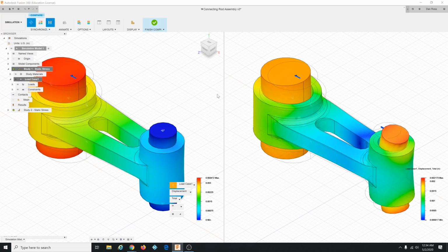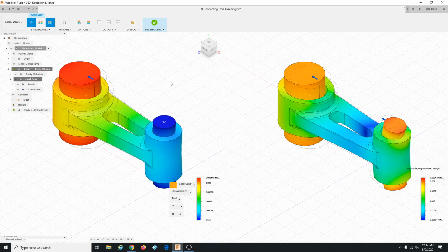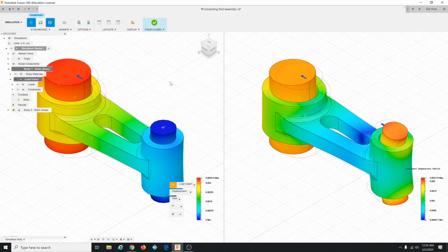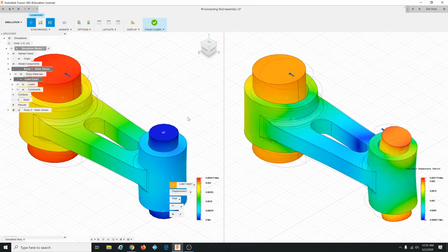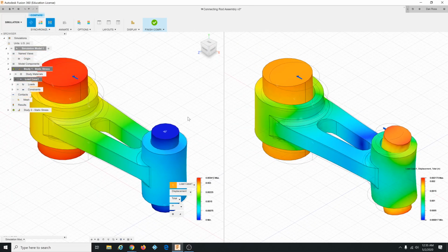Anyway, that's the basis of stress analysis. The more you're trying to optimize a design, the more important it is. Like aircraft are highly optimized. You want an airplane to be strong enough and not a whole lot stronger than it needs to be, because that just adds weight. So safety factors are 1 point something, maybe 2. It depends. Like if it's the wing spar, you don't want the wing to break off, so you might have a little bit higher safety factor. But anyway, a lot of times you just make the part really big.